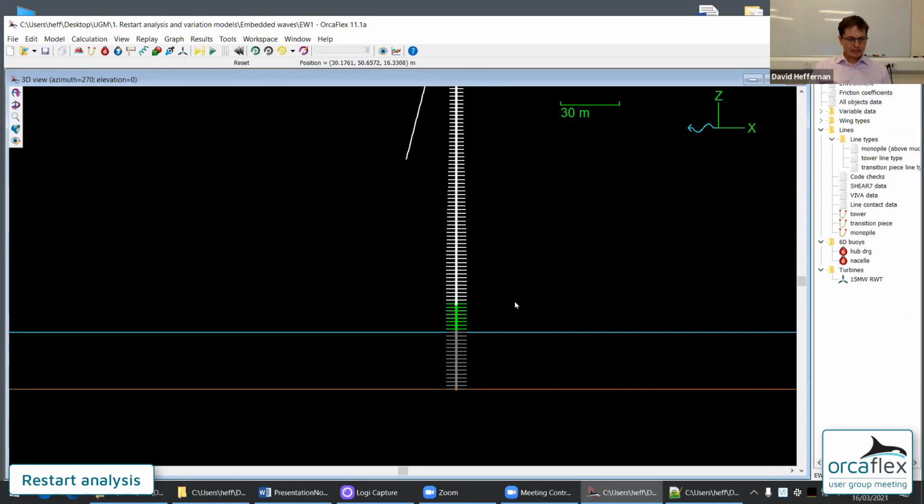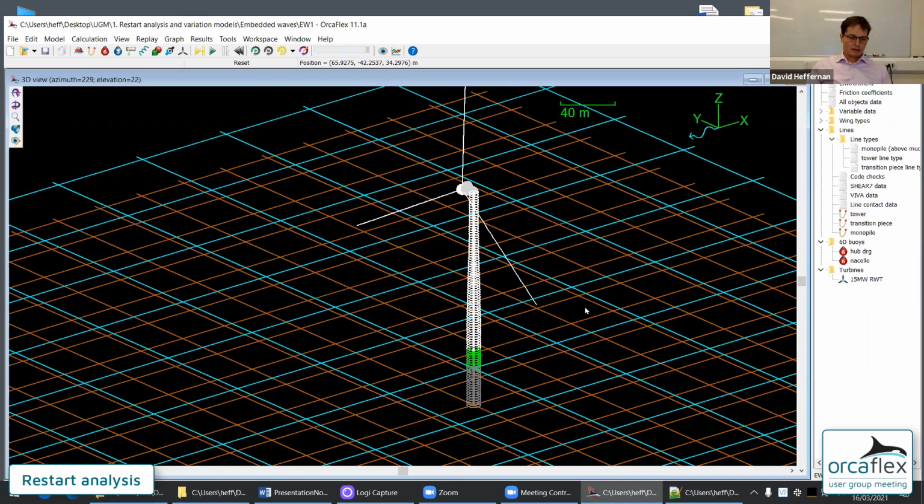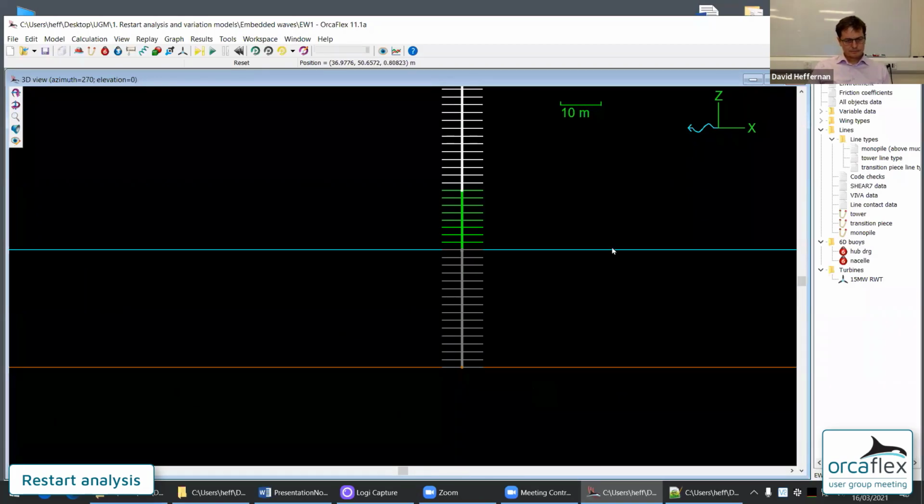What we have here is a fixed foundation offshore wind turbine. It's a monopile, and the IEC design code for these things has a requirement that you assess the impact of extreme waves, accounting for both the stochastic nature of the environmental loading and the nonlinear nature of the waves. Now, irregular waves are typically modeled using an ensemble of linear wave components.